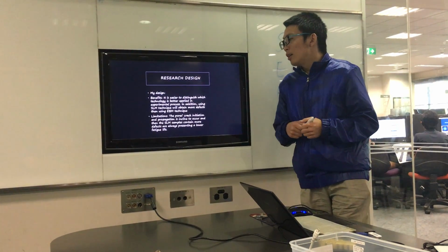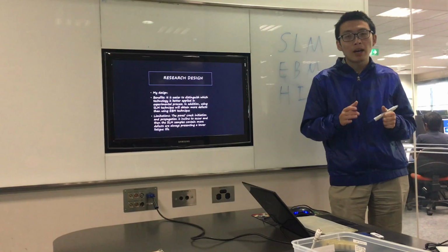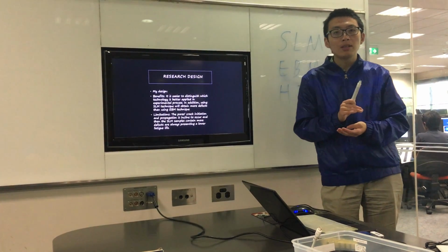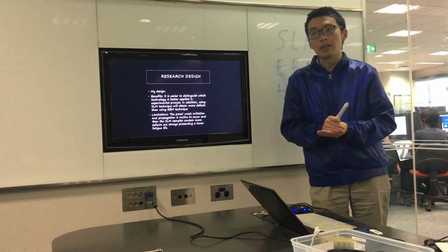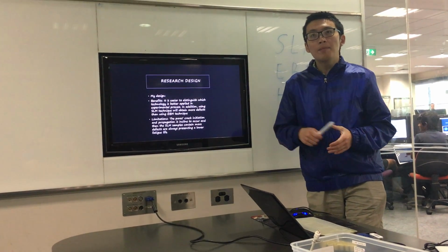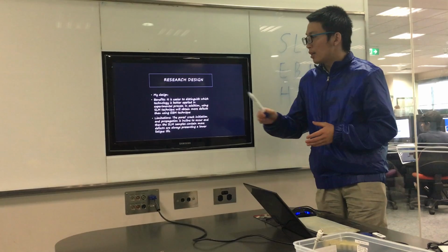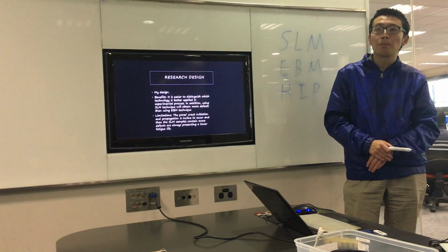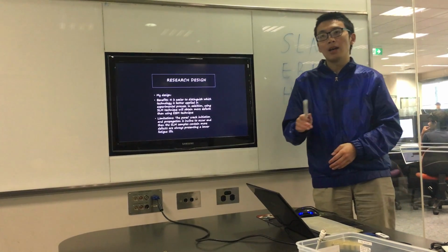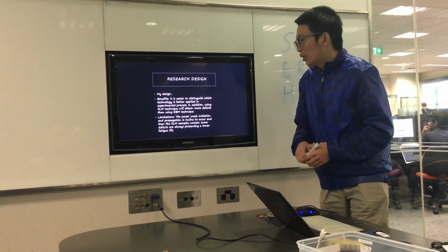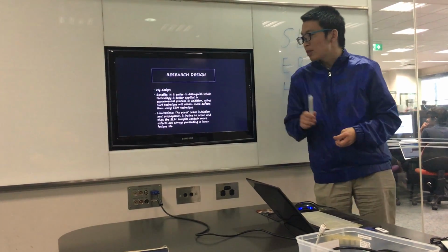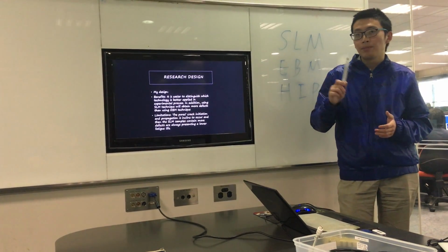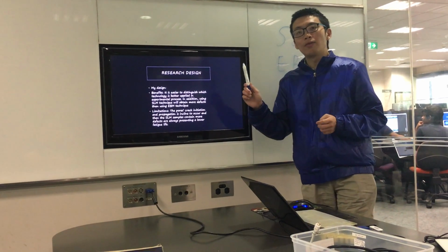In addition, using SLM techniques will obtain more defects than using EBM technique. The limitation of my design is that crack initiation and propagation are inclined to occur. The SLM samples contain more defects and always show a lower fatigue life.